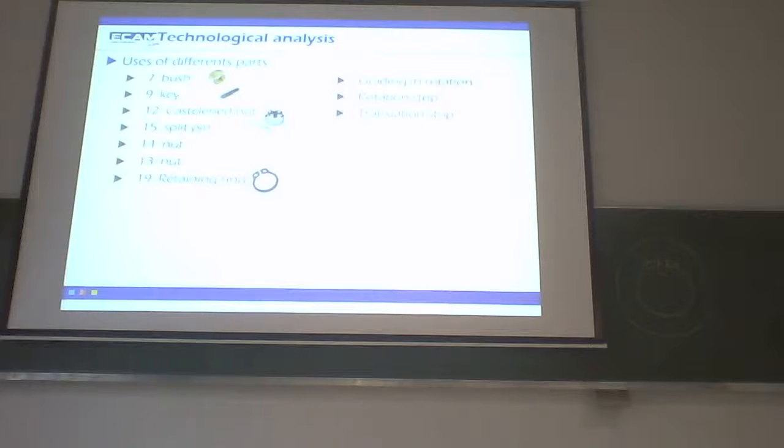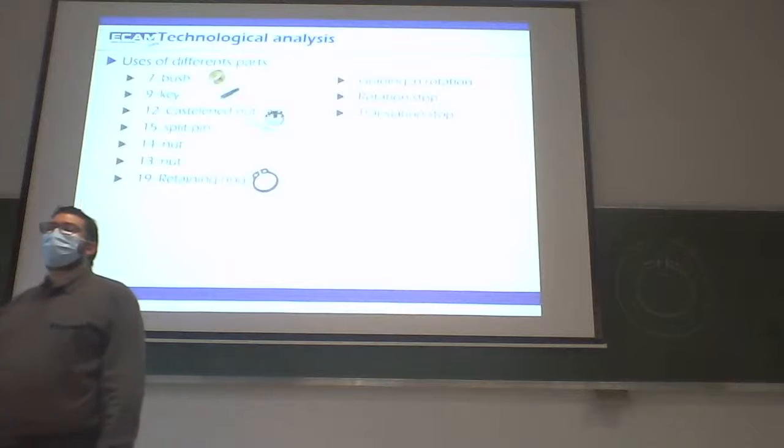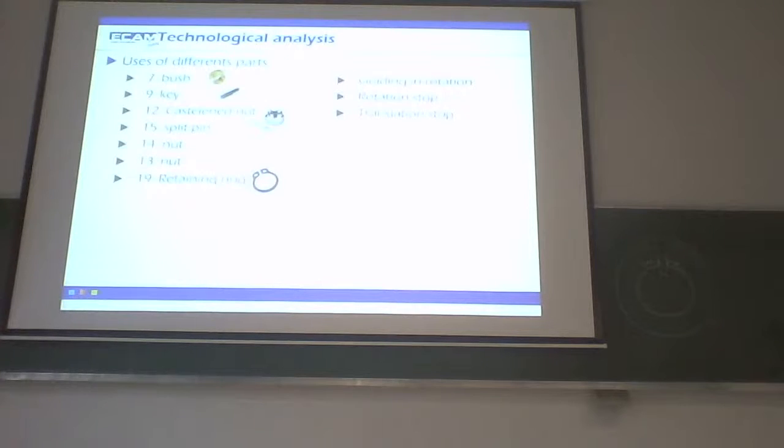An elementary element, a standard component, is always used for the same thing. A key: rotation stop. A bush: guiding in rotation. A nut: maintaining position, translation stop. You need to learn that.